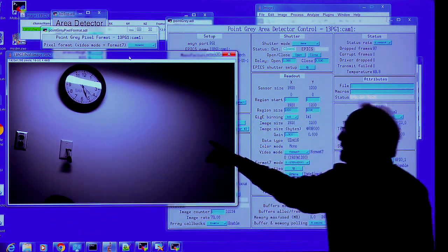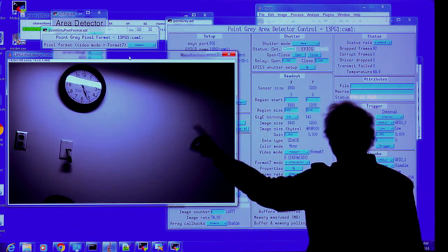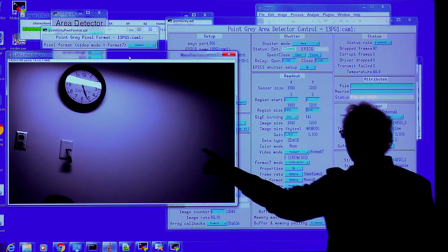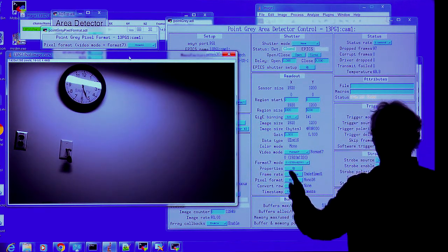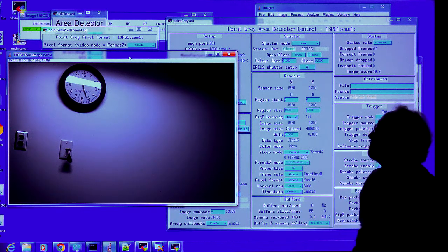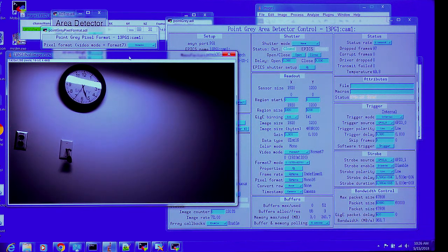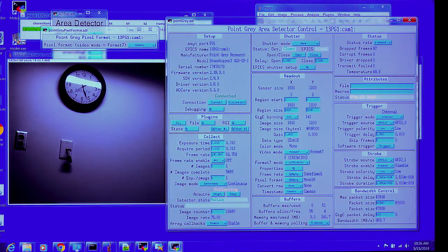If this were Channel Access, that wouldn't have happened, right? But because this is PV Access, it's now sending a 16-bit array instead of an 8-bit array. And it can't quite go as fast. It slows the camera down a little bit to go at 16-bit mode. Can you do the same on the status? Yes. Change the color mode, apply? Yep.